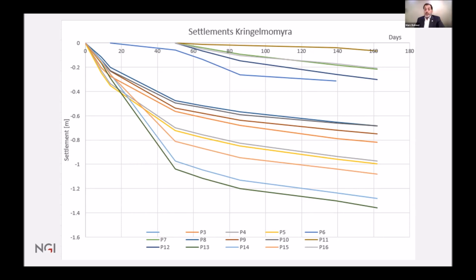Just to make sure I understand right, you have telltales like tubes where you measure the lower part, and then you measure from the top, which are the curves starting from 50, right? Well, I think they're slightly different. The lowest ones are settlement plates underneath the fill, and on top, I think they're just measuring specific points, like settlement bolts. So whatever deformation is in between is the self-settlement of the fill you're putting?